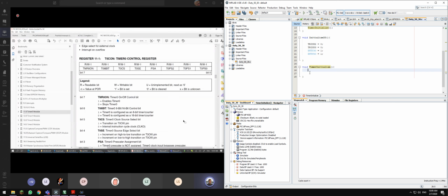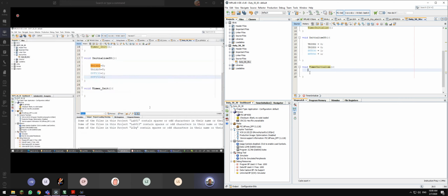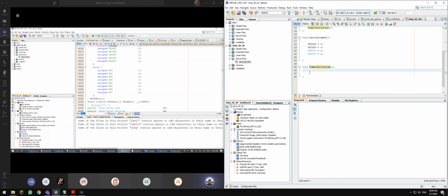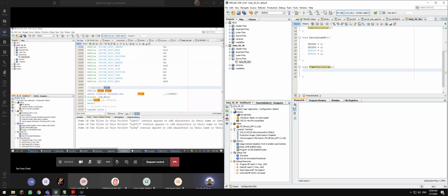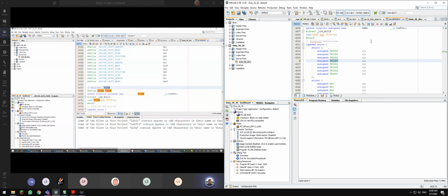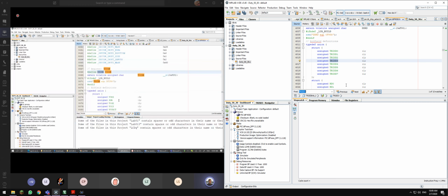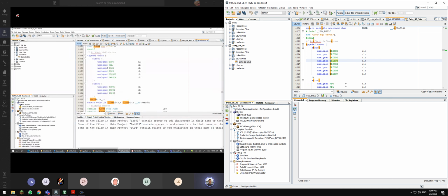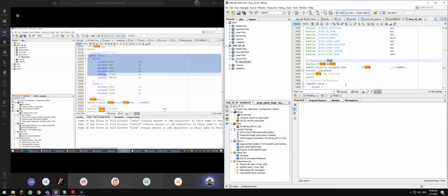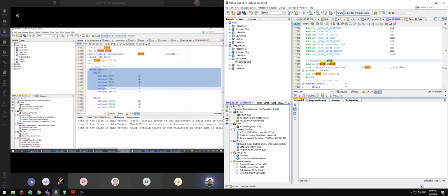So basically, that's all. Let's say I don't know how to type the special function register. Never mind, I just copy this. Come back to our MPLAB X, go to the PIC18 definition, and Control V. This is the T0CON. These are the T0CON registers. You see or not? They define a union of structures.